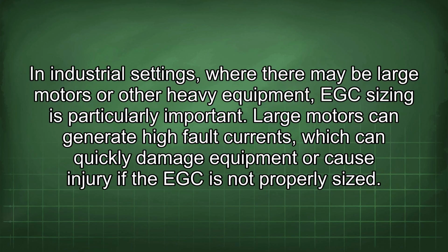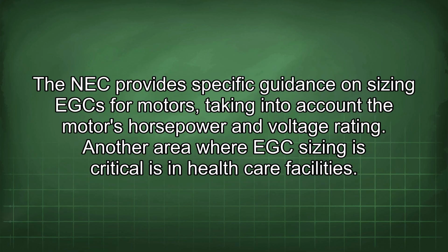circuits. In industrial settings, where there may be large motors or other heavy equipment, EGC sizing is particularly important. Large motors can generate high fault currents, which can quickly damage equipment or cause injury if the EGC is not properly sized. The NEC provides specific guidance on sizing EGC for motors, taking into account the motor's horsepower and voltage